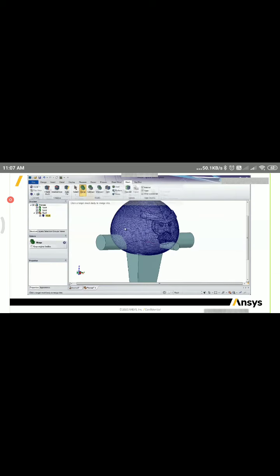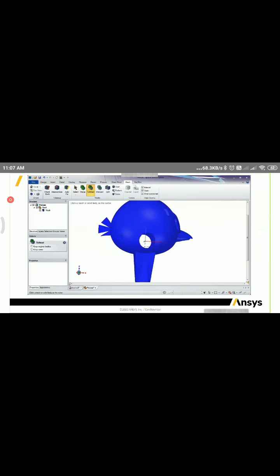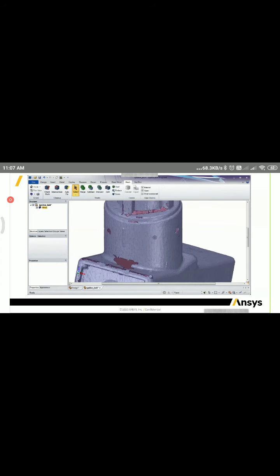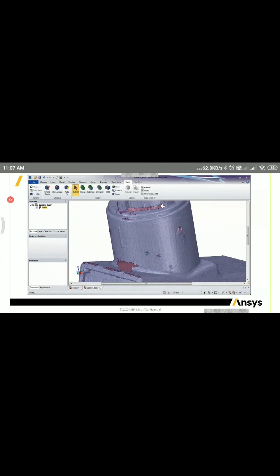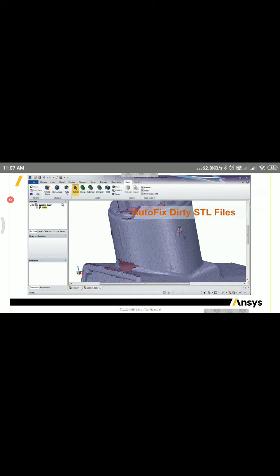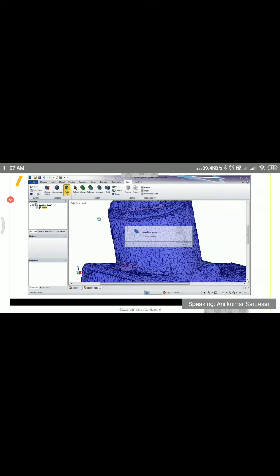So this video will talk about how you can prepare your model for 3D printing. Here you can see you have 3D geometries as well as surfaces and data where you can do different merge and subtract operations. If there is some corruption, you can go and do automatic fixing. You can see it's trying to do everything automatically. We can add the surfaces, we can create the geometry, we can fill, and at the end we can merge them together to get the final output.